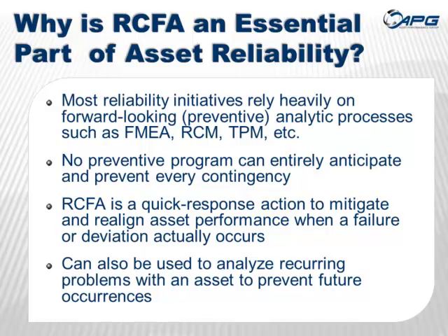Another use for RCFA, as you can see in the last bullet here, is whenever we have recurring problems with an asset, we can identify predominant failure modes using RCFA, which will be used to help prevent future occurrences. So I think RCFA is a very powerful tool in an asset management program that can be used to address problems when and where they occur, as well as preventing future problems in connection with our forward-looking reliability tools such as FMEA and RCM.